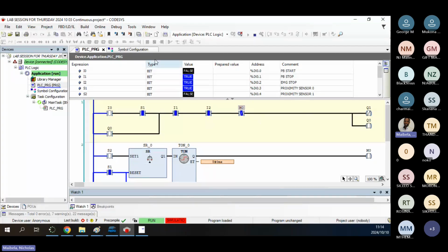So from FluidSIM, the contact was normally open, meaning it was off. But here in ladder logic, you have to convert it to a state of on. And hence CODESYS knows that it's off that side, but when we negate it here, we are putting it on.